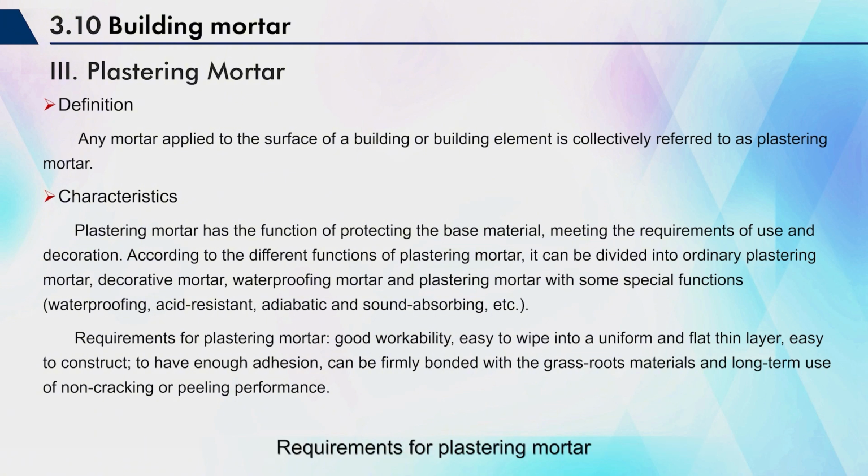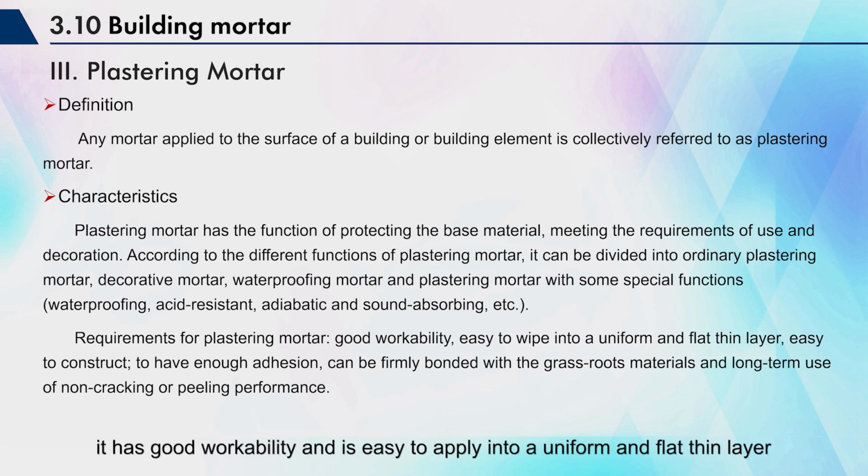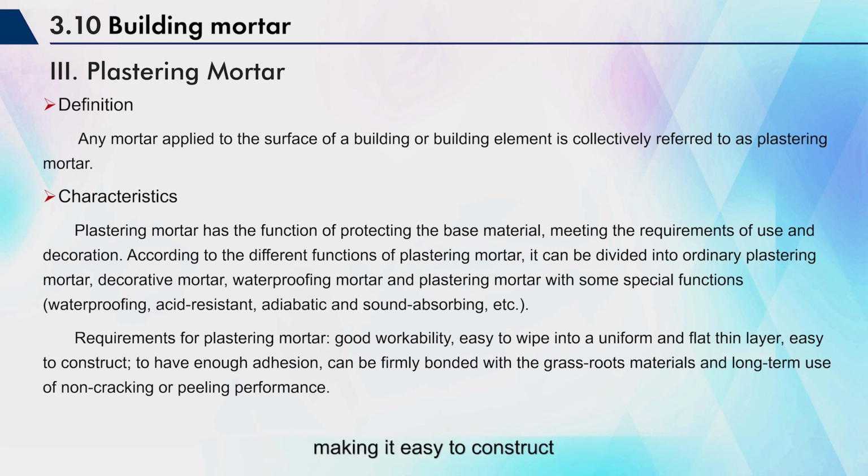Requirements for plastering mortar: it should have good workability and be easy to apply into a uniform and flat thin layer, making it easy to construct. It is necessary to have sufficient binding force, which can firmly bind with the base material and prevent cracking or peeling after long-term use.